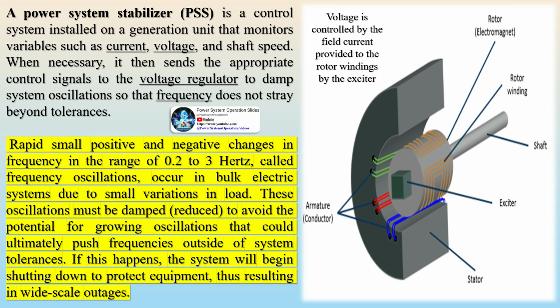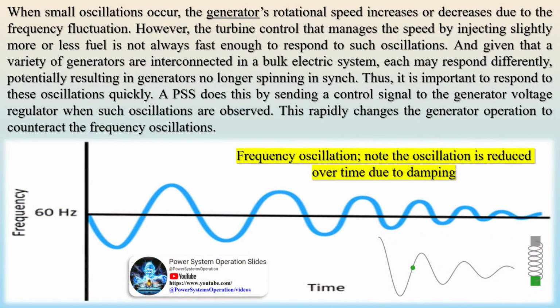Small signal stability performance tested the transient stability performance of the PSS and its performance during system islanding. This highlighted the importance of choosing appropriate washout time constants, stabilizer output limits, and other excitation system control parameters. The frequency response method used to compensate for the lag between the excitation input and the electrical torque was fairly robust. Chow and Sanchez-Gasca proposed pole placement techniques for designing power system stabilizers, emphasizing the frequency response characteristics of the controller and suggested a simple procedure to obtain controllers suitable for multiple operating conditions, ensuring desirable frequency response characteristics.